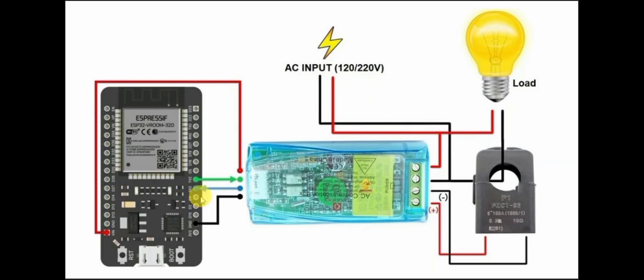Pin RX of the module goes to TX of the ESP. The ground of both devices must be connected together.